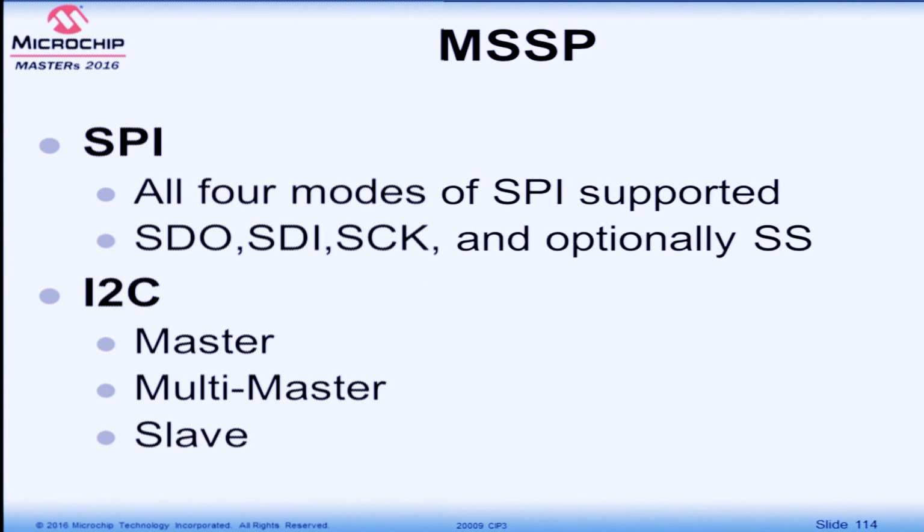For SPI and I2C, we actually call it an MSSP module. For SPI, we support all 4 modes of the SPI operation. We provide SDO, SDI, clock, and optionally an SS pin. For I2C, we have master mode, multi-master mode, and slave mode supported.